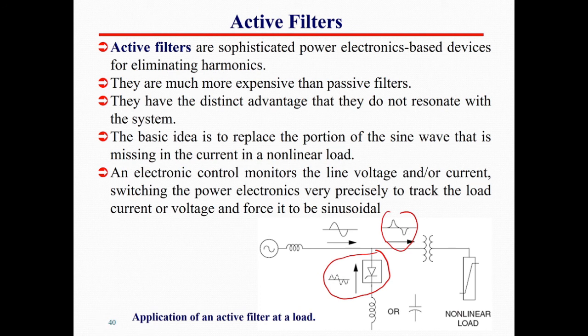But over here, what we are doing is connecting what we call an active filter. The active filter will provide the harmonic current, so that the current taken by the non-linear load, which is non-sinusoidal, will be compensated such that the main current taken from the source will be sinusoidal.